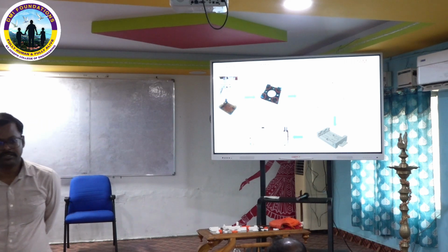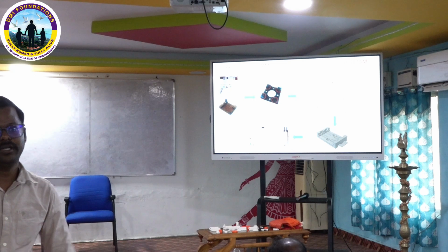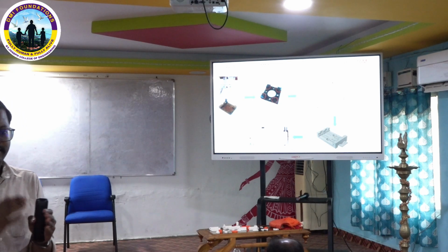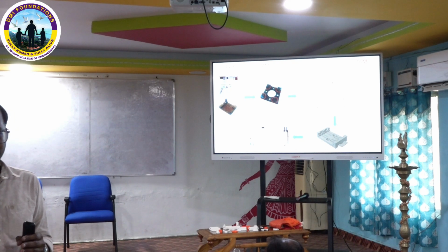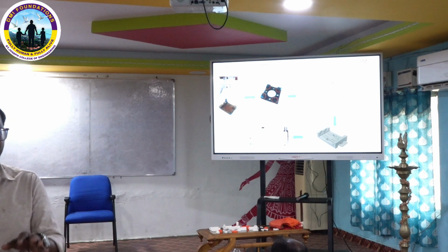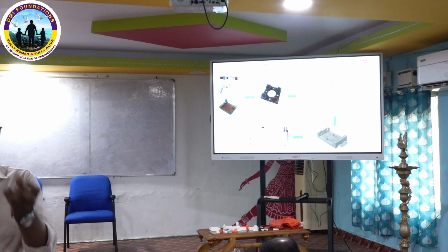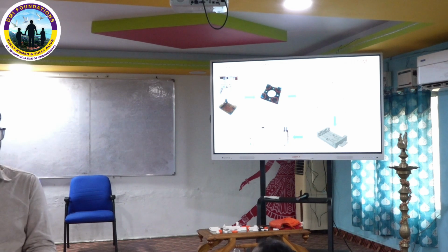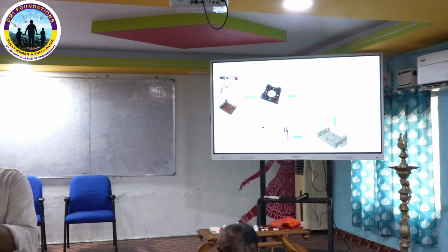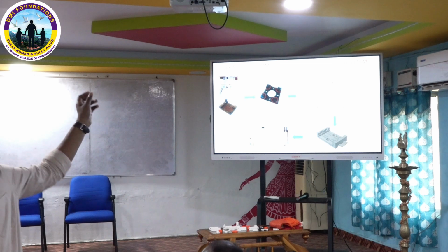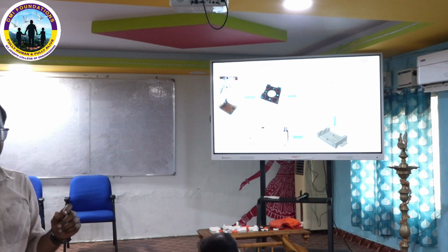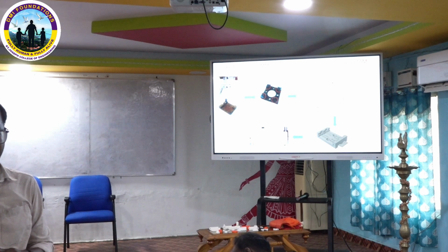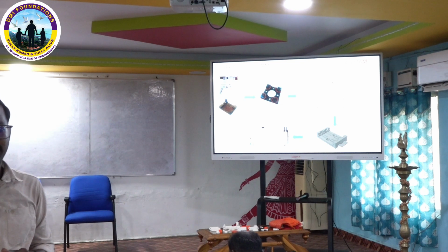Relative density 10%, 20%. How were these selected, with what reference? Actually, Gibson stated that above 30%, the structure behaves as a solid structure. Above 30%, the material property will be more and the structural property less. So I took 10, 20 and 30%. For each structure there is an equation to calculate the relative density. For each structure, I fixed the length of the strut and changed the cross section diameter of the strut.